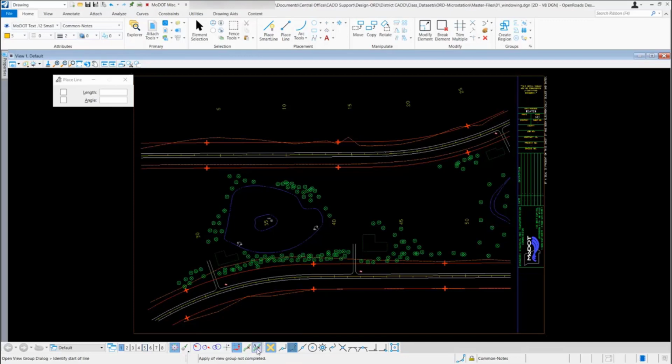And then after your Civil AccuDraw toolbar, you have your AccuSnap toolbar. You can toggle it on or off here, and then you have all your different snap modes listed after that. And we have a whole section on the AccuSnap toolbar a little bit later on.